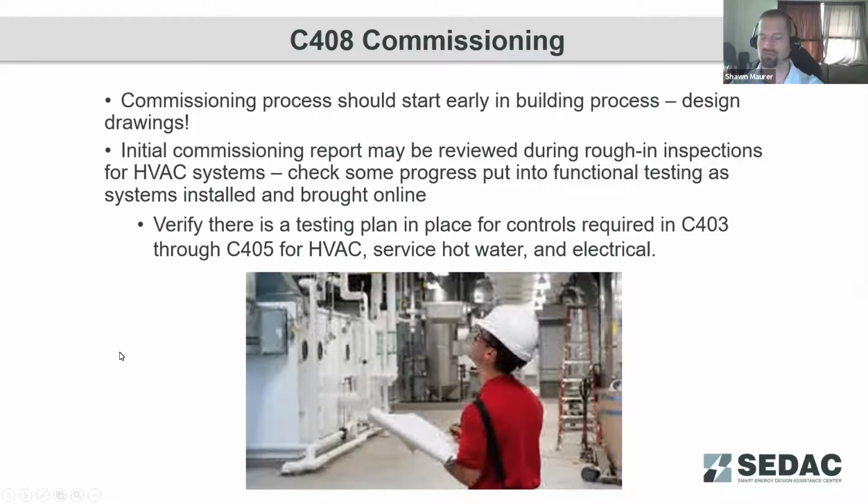Usually what we see is in control drawings. As those are developed, they're also used to develop commissioning checklists. So as you have sensors for controlling an HVAC system drawn out, those sensors get documented that they need to be tested and verified. The control sequence gets documented, how the sequence is supposed to work. Those all get drafted into a commissioning plan. The commissioning plan documents all those different sections of the control sequence for that equipment. And then that is what the commissioning agent will then go back through and use as the commissioning checklist.